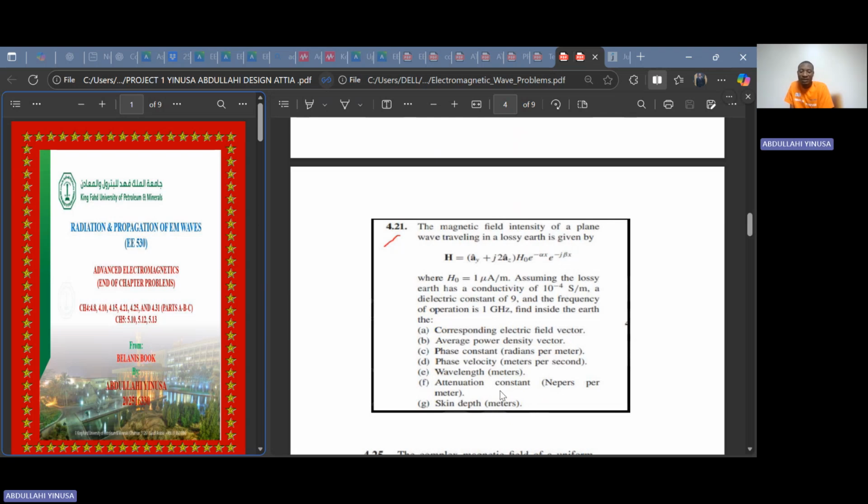So the formula for the attenuation constant when it is what? When it is either a perfect dielectric material or it is a perfect conductor, in nepers per meter. When they ask us to find it in decibel, we are just going to take the 10 log of the answer, then you're going to get the answer in decibel. The wavelength does not change, that's 2 pi over beta. However, the beta we are going to be considering here is going to be what? The beta in the lossy media, and then that of the lossy media, that's what?